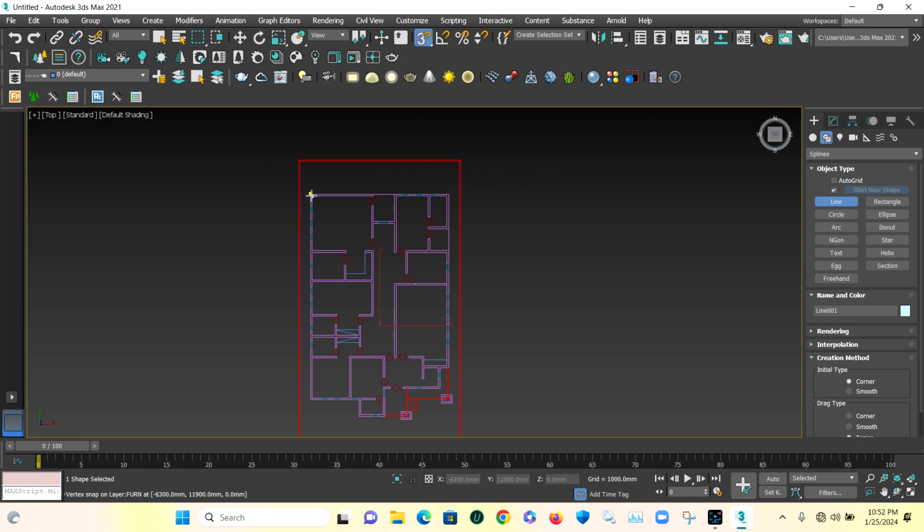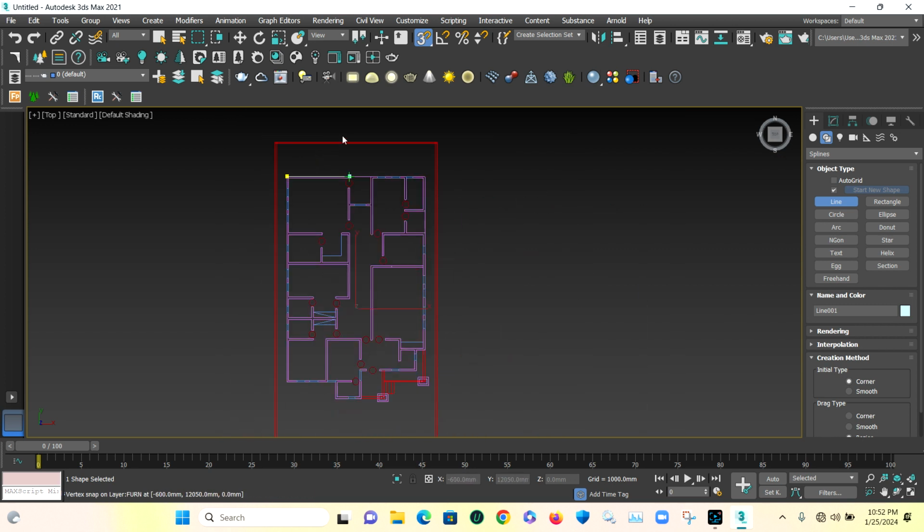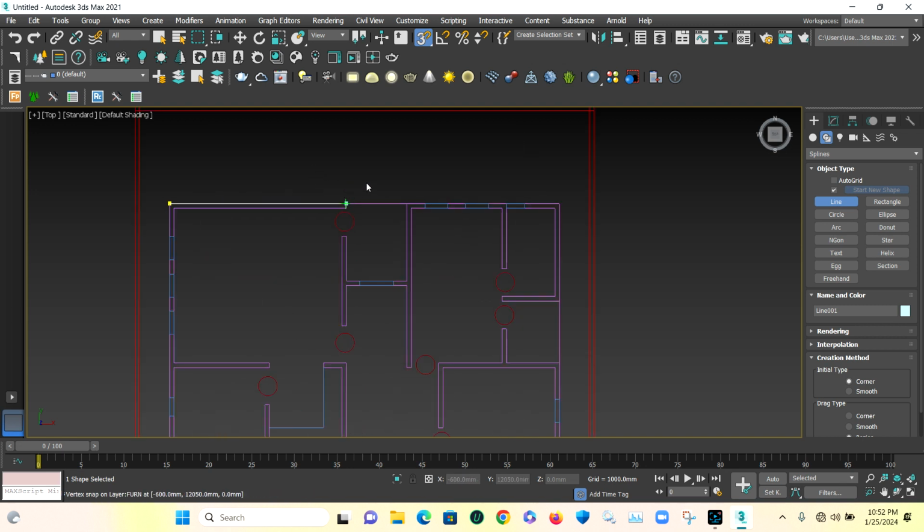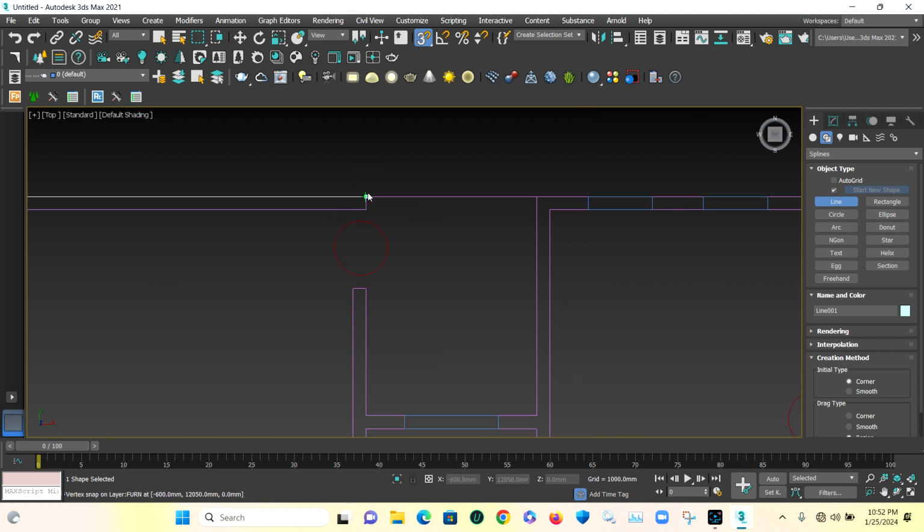But once you release shift, you're moving around on all angles. So to avoid mistakes, you just hold shift, except when you are working on a path that is not straight. If you have a circular path, you can leave shift and just use snap to get them. Now I'll hold my shift while I trace along the external parts of this drawing.